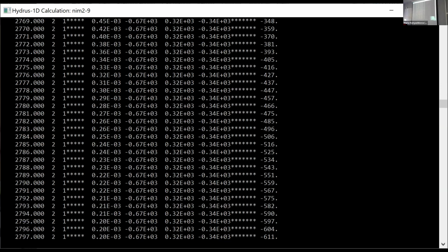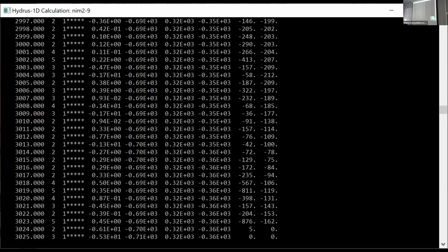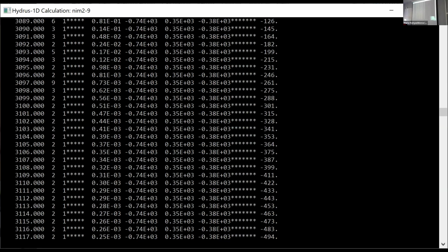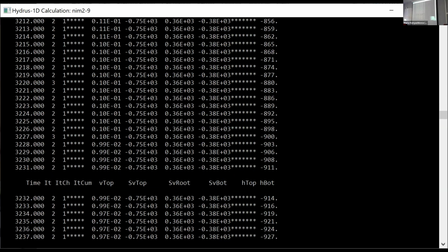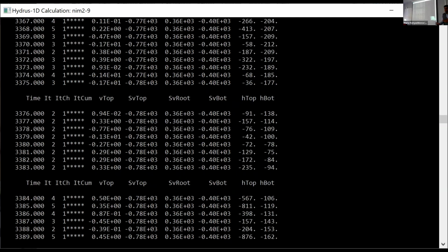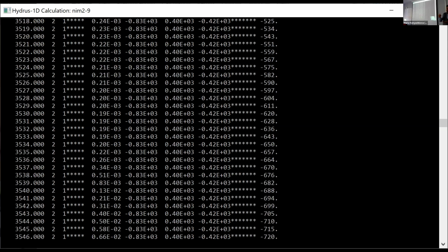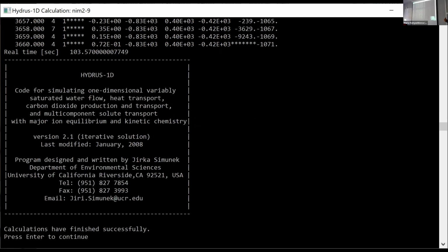Actually, we can do it for drip irrigation. We divided the amount. We should calculate how much water we want to use if we use the drip or tape as a different irrigation system. So the amount of water should be calculated based on each dripper, and so we have to know how many drippers we have in the field. Just do it and compare with the data set that I provided you.